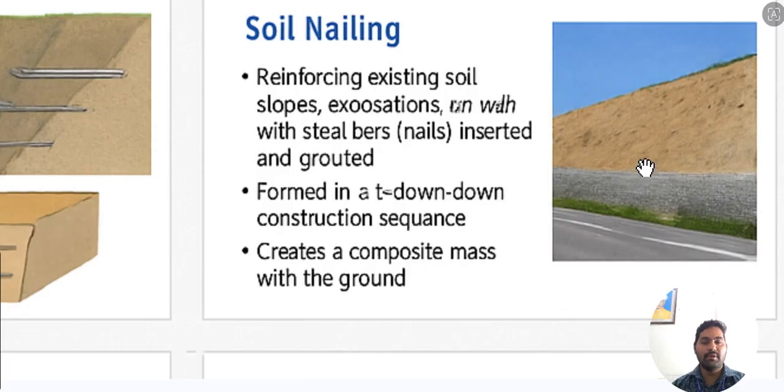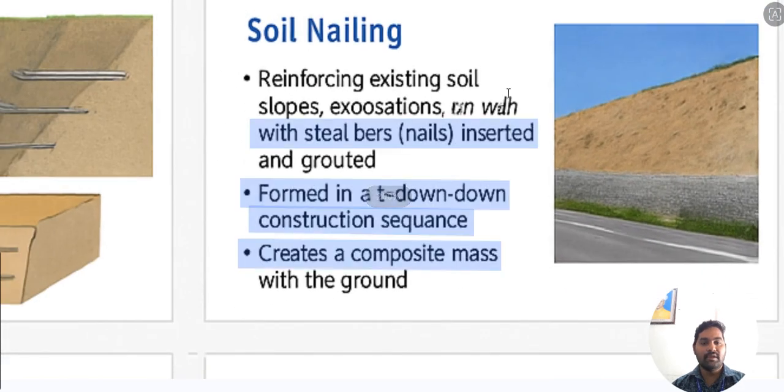So we need to locate the sloped surfaces that may not resist weathering factors and are not stable. At that moment we go for soil nailing. If you see this figure, you can understand easily. This is a sloped area that is unable to resist weathering factors, so slowly it can fall down. That's why we introduce the nails, likewise in the above method.